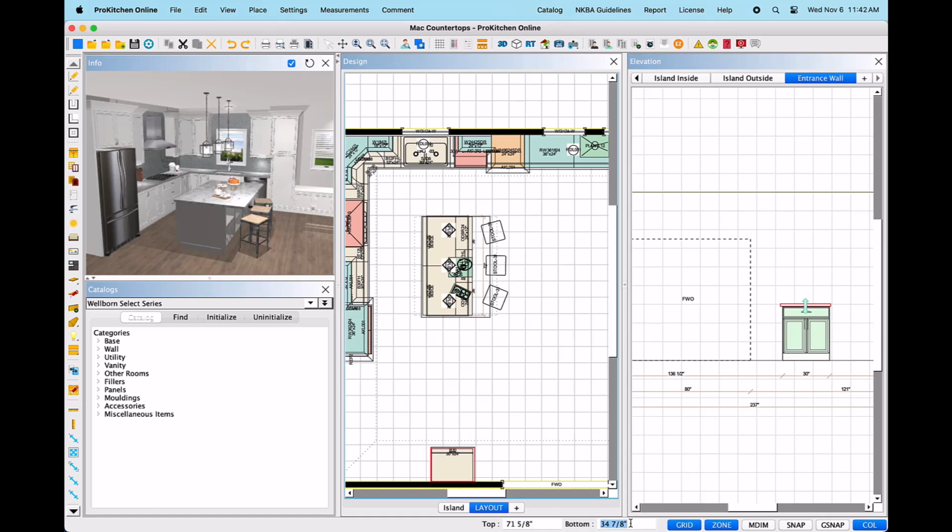Back in the right-click toolbox is the Copy tool. This tool may be used in both the elevation and plan views. Left-click to select, which will copy the countertop with all the dimensions, attributes, and up-down placement intact. The mouse will turn into a crosshair with the copied countertop attached. Left-click in either view, then move the mouse to the desired location and left-click to secure.